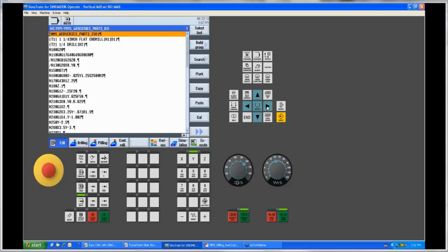So this would be traditionally how you would see the file possibly come in. A lot of times you will see an O and a number. We don't need that. You would take the O number off. But other than that, this would be a very traditional FANUC protocol. If we come down and take a look, our M6 string, our G43 H1 to call up our height offset for tool 1, our G41 with the D protocol call to call up the diameter of tool 1.